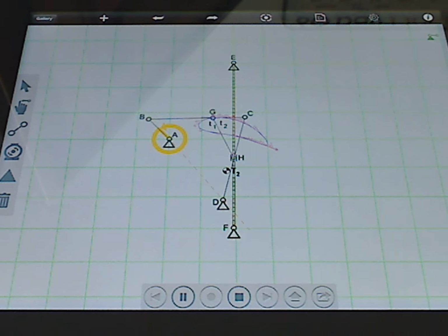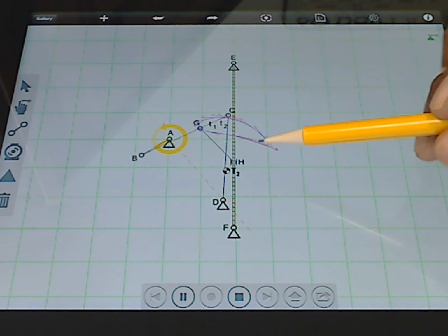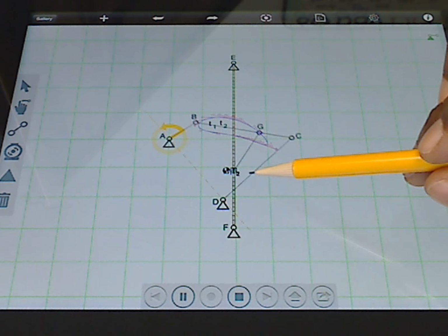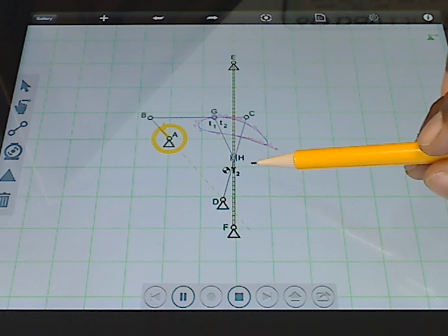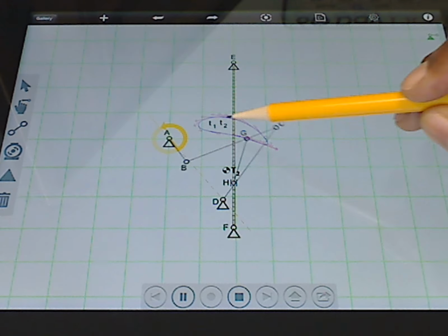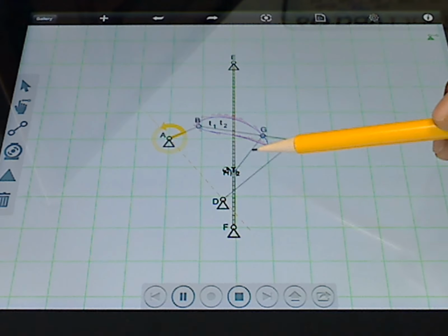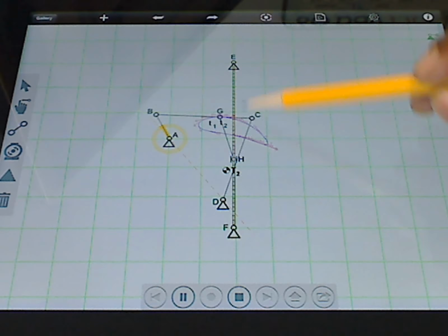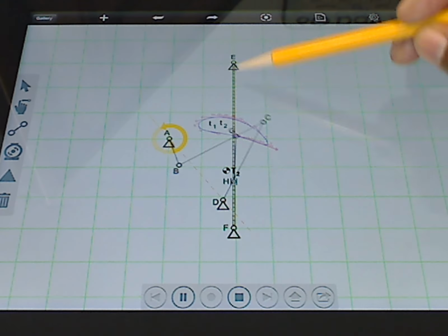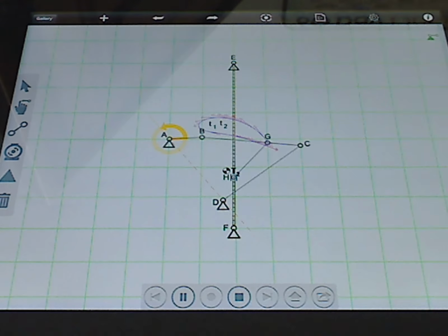And we can see that in a second here. And so you see point H moving. So it goes down. That's the maximum stroke. Then it's coming back up. And it should be stopped, but it's still moving, still moving, still moving. And it paused just for a second right over here. So that shows really that either my radius is wrong or my position of this straight piston guideway is at the wrong location.